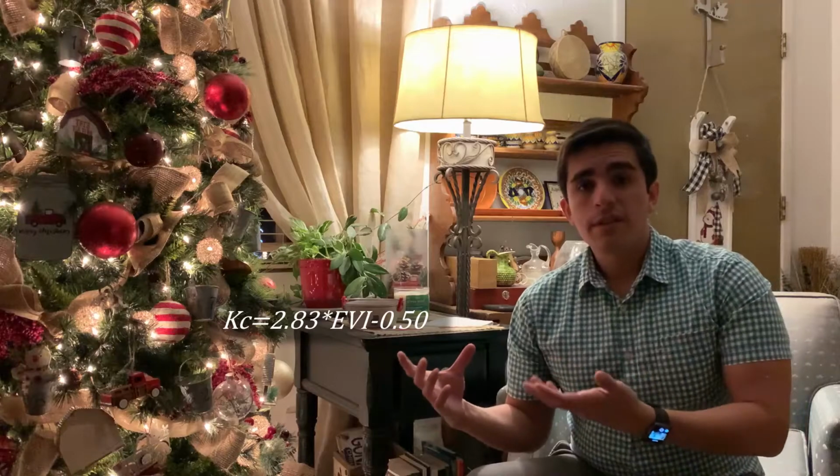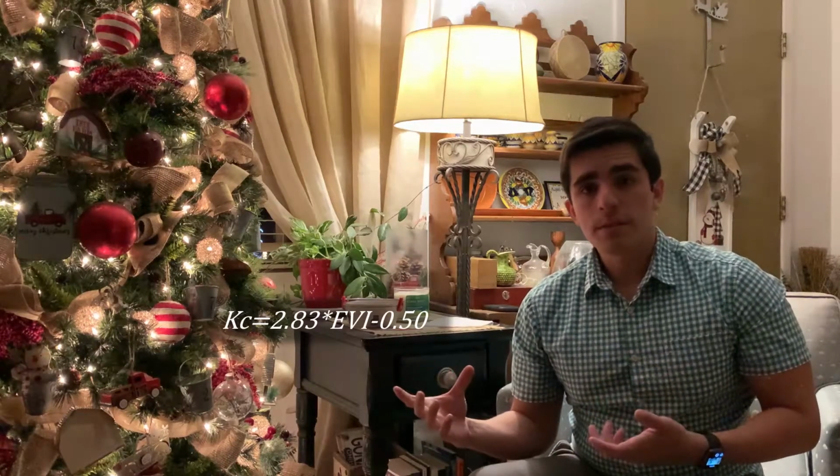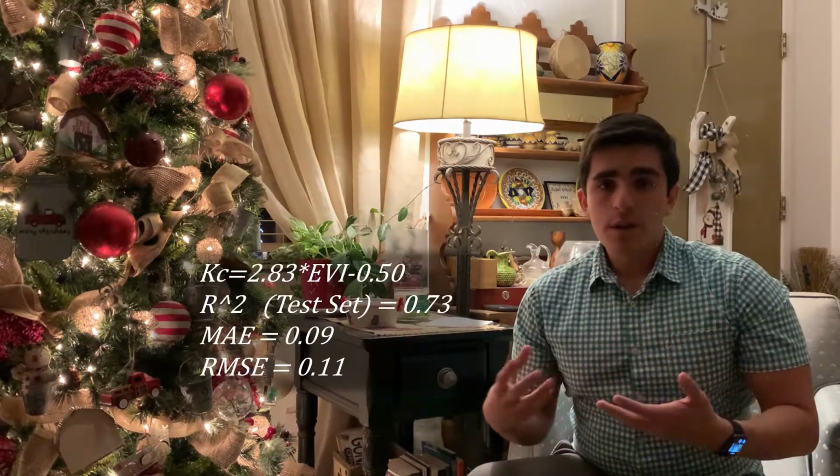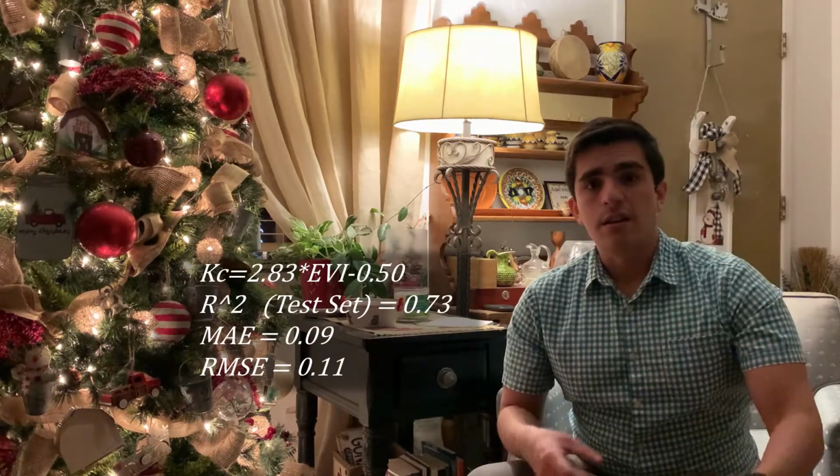We derived this equation using an ordinary least squares method, and the equation itself has a plus or minus 10% error. Therefore, estimates should be used with caution. As we stated earlier, ET0 can be calculated with any basic weather data. We can now calculate ET using this equation. Again, we get ET0 from any basic weather data, and now we have a function that predicts Kc. Kc itself could be derived from most remote sensing platforms which have worldwide observations.